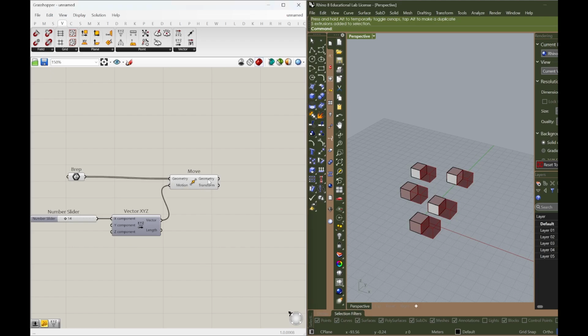As you can see in the geometry, there are 5 closed Breps. And in the transform, it explains what each object is doing. There's another way to look at this list. If we type in quotation marks, we can get a panel. And if we wire this into the panel, we can see the list of items that is being used. However, when we delete items from the list, we'll notice that it actually creates nulls, and it also creates a warning for the Brep.